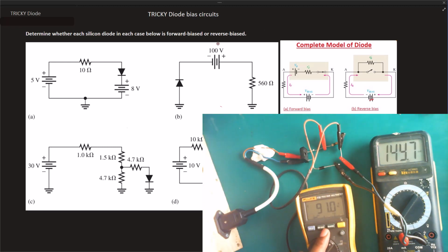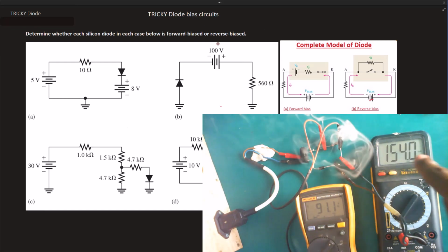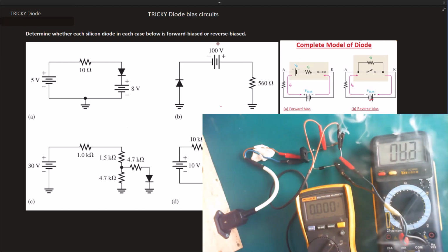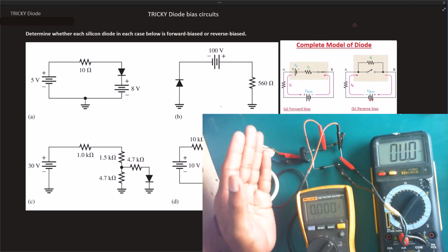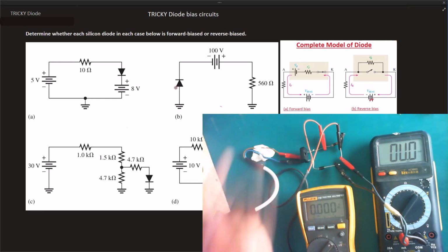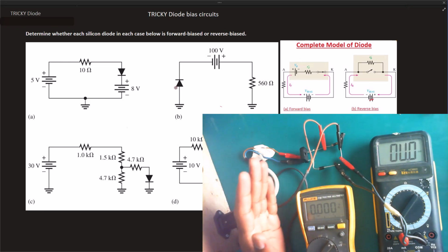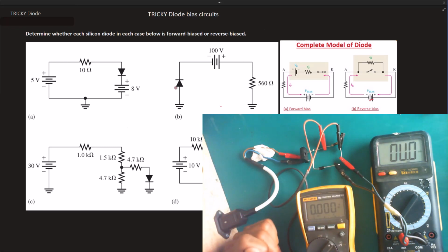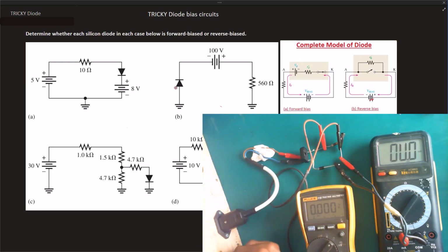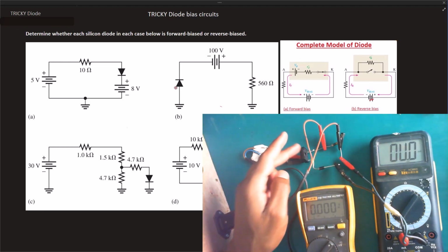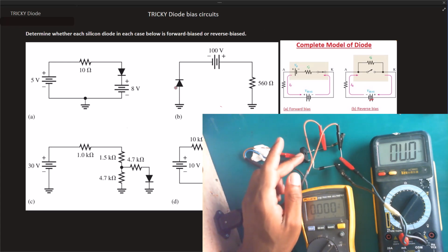So it's 90 volt across that resistor and 150 milliamps, so it's smoking. So you can clearly see, right? What's happening here is we're feeding in 100 volt. Now the 100 volt was an open voltage that we measured. There was no current flowing through. Which basically means when there is some current flowing through, that 100 volt will drop across the diode inside the bridge rectifier.